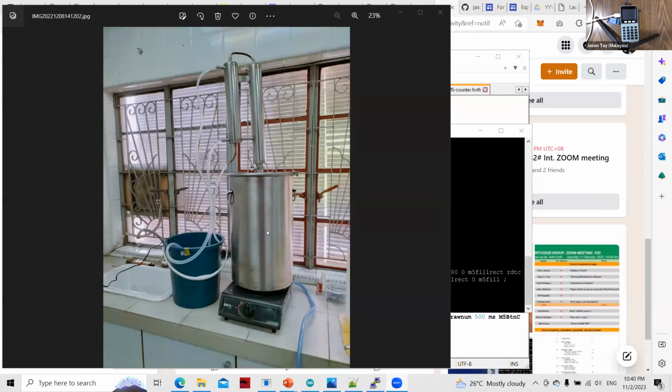Normally, I suppose with a bigger setup, this would be called a reflux column. This first column here is what you would pack with, say, copper wool, and that creates a larger surface area. It also pulls sulfur and other compounds out of the vapor, and it encourages greater condensation of the water vapor, which falls back down again, so that it is mostly the ethanol that passes through into the condenser on this side, which has cool water pumping through it.